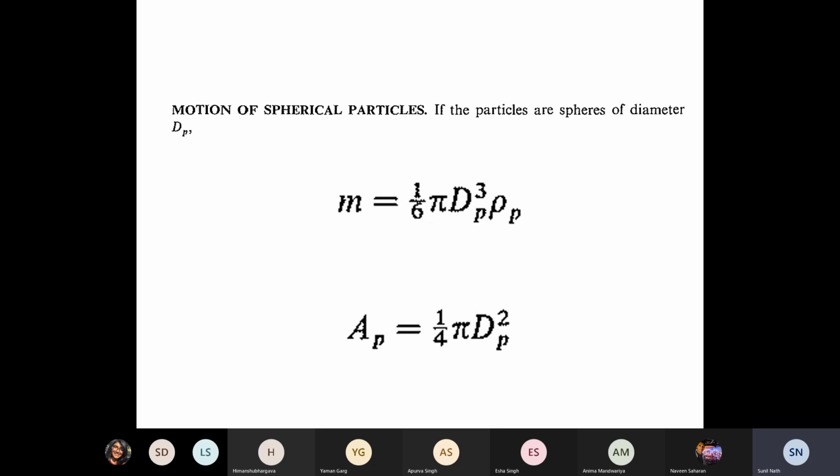Start from the general expression for the acceleration, write it for both the cases of gravity settling and the radial movement in a centrifuge, then put the du by dt term negligible, equal to 0, then solve for the maximal velocity for shape independence as well as regime independence, then obtain the general equation for a sphere for any Reynolds number, then further limit it to creeping flow with the inverse dependence of the dimensionless drag coefficient CD on the Reynolds number and obtain the Stokes velocity.